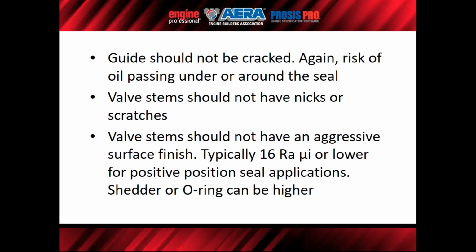Valve stems, again, we're stepping away from the seal a little bit, but it still has impact on the performance of the seal. So if we're reclaiming valves, and even new, with shipping and handling and things of that nature, valve stems should not have nicks or scratches that are going to travel through that seal lip area and potentially damage the seal lip or create a direct leak path.